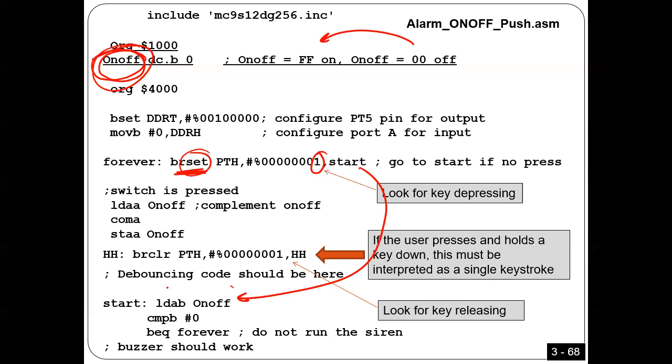In start, I'm going to check the steps. I'm going to ask the variable: is the system on or off? It's going to tell me, okay? That's what I did. So number 1, this is the first case. When I check the pin and I see 5 volts, that means the user didn't press. So that means you did not change the status of the system. So I'm going to come here to check the variable. If the variable is 0, that means the system is off, so I have to come here. Otherwise, come here because the system is on.